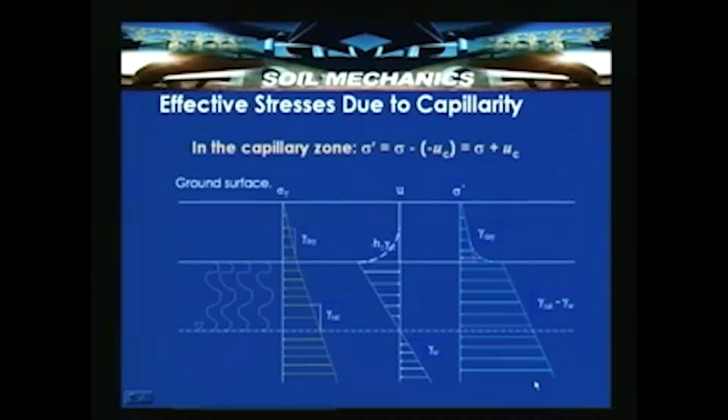this particular distribution. So, one has to keep in mind that this capillary saturation is not generally considered in design, because in the case of, say, any flooding or any evaporation, particularly when this is evaporated, this effective stress can be lost. So, as it is subjected to climatic conditions, it is very difficult to consider and keep this in the design.